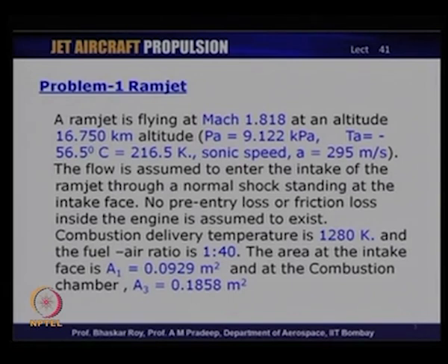Now, the flow is assumed to enter the intake of the ramjet through a normal shock standing at the intake face. So, the entire shock structure there is simplified into one single normal shock, and analysis through that shock would suffice in solution of this problem.